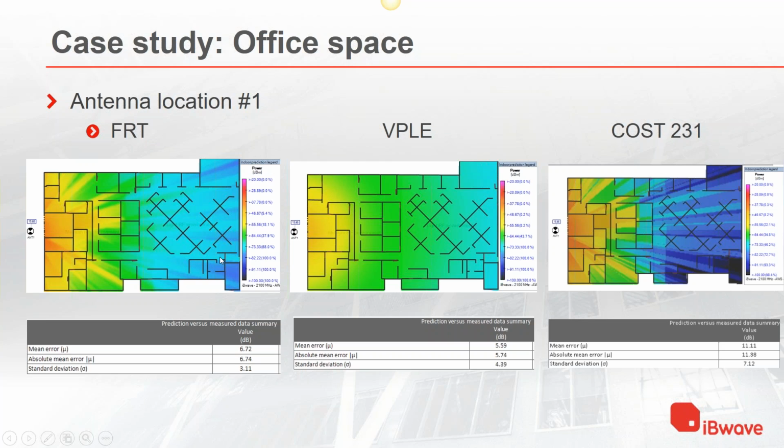And so really what you will have is interference signal coming from this antenna, assuming there would be another one right here that is fairly high. And that would affect your signal to interference and noise ratio, or co-channel interference if you are a Wi-Fi guy. Whereas here, you would just say, oh, that signal is just way too low. It will not affect my co-channel interference or SINR.